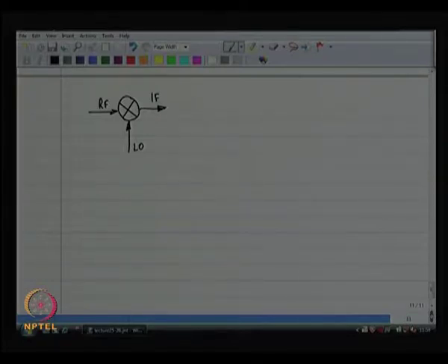So, let us first try to understand this. Let us take an example. Let us say that the RF is at 1 gigahertz and the LO is also at 1 gigahertz, which means I really want DC at the output. This kind of a mixer would be part of a direct down conversion receiver. Okay. So, one step single shot direct down conversion receiver, also called a homodyne receiver.